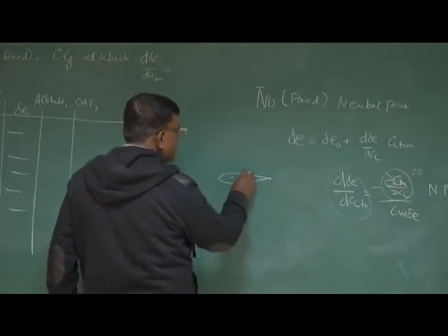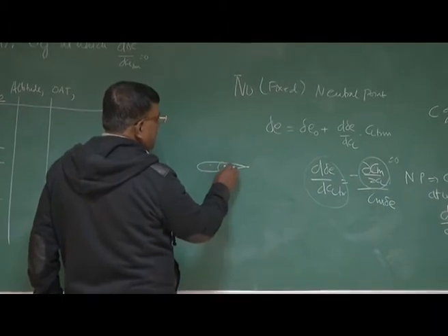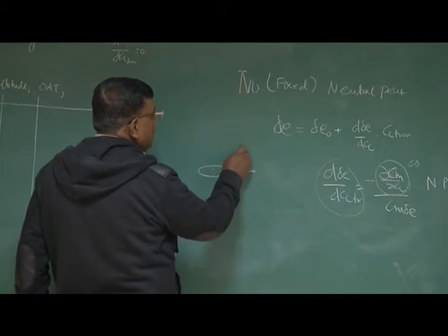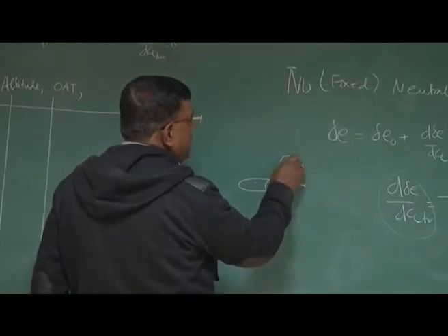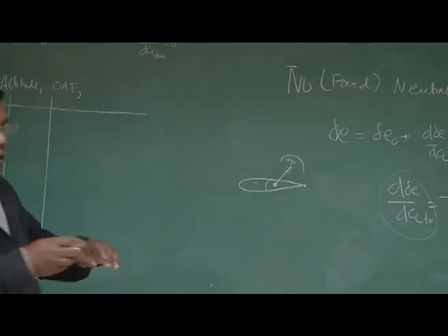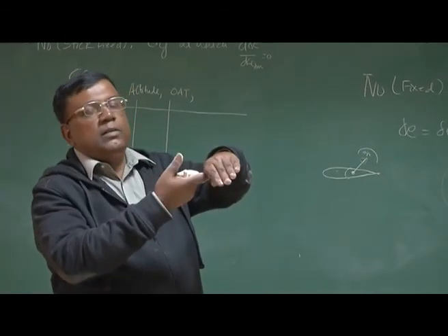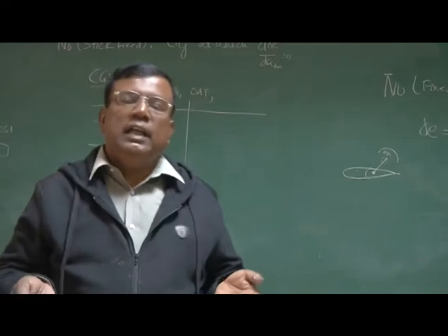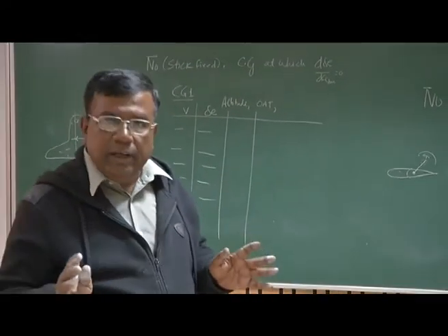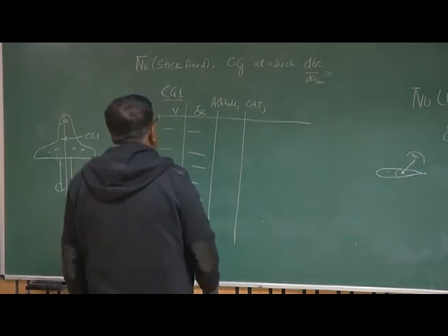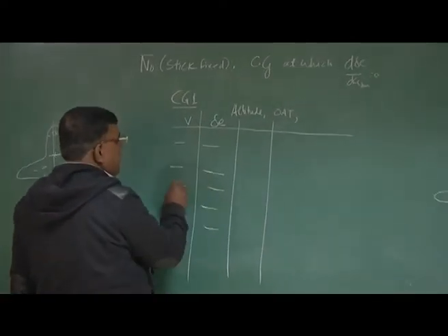So this is the elevator part, and as it rotates a potentiometer. Okay? So this is the potentiometer shaft. As this elevator rotates, the potentiometer also rotates. This gives you a voltage, and that you can calibrate and get the deflections, right? So we assume that delta E is also measured, and I do this experiment for different trim.